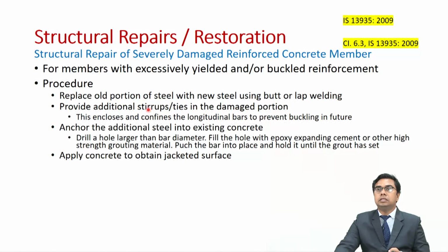Then we will provide additional stirrups or ties in the damaged portion. This will ensure that the longitudinal bars are effectively confined and enclosed to prevent buckling in future. We will anchor the additional steel into existing concrete.